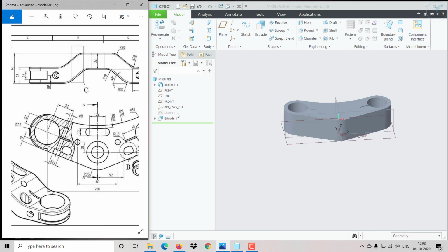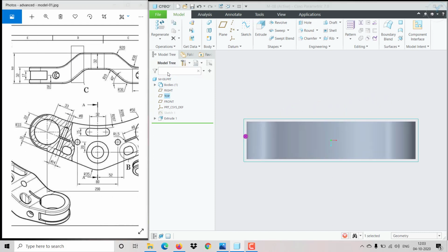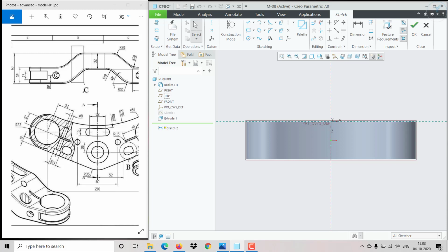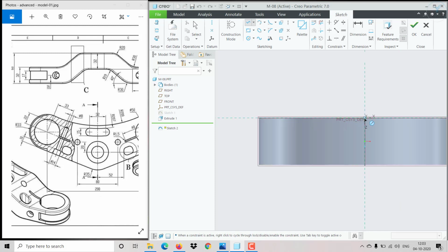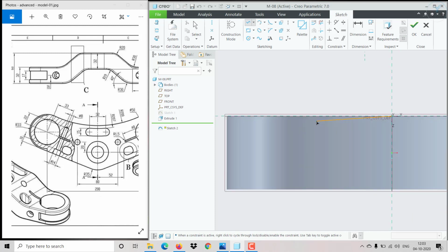So select the top plane and go to normal. So now we need to make cuts over here. So you can draw a simple line from here straight. We don't know what, now just push in somewhere and make it a little bit inclined, and then draw it like this, exactly straight. Make up to end also, no issues. So later we can decide that. Escape. So now delete this line because we need this part only.